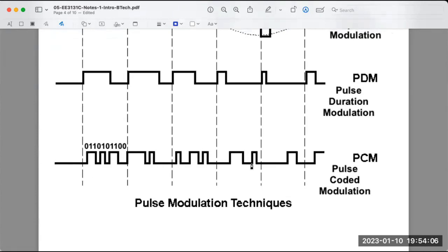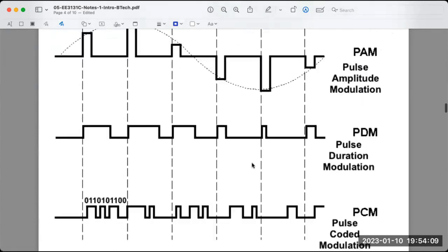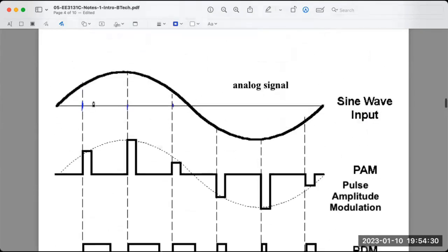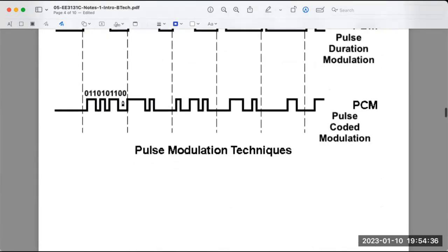If I now quantize value as well, remember in the other example when we had 4 values, I had 2 bits. Suppose in this instance I have 1024 levels. Then I can represent each level by 10 bits. So here are those 10 bits. Suppose that this height falls into the bin represented by this 10-bit pattern. So now I've converted this value to these ones and zeros.